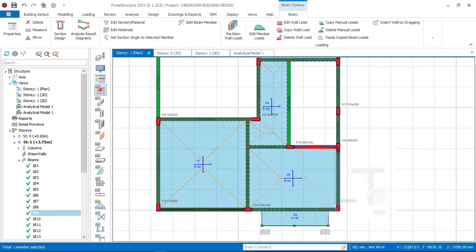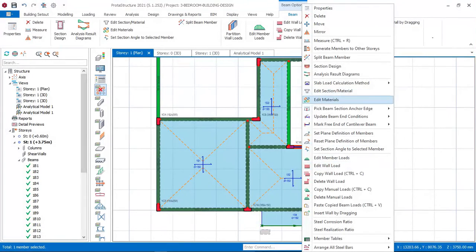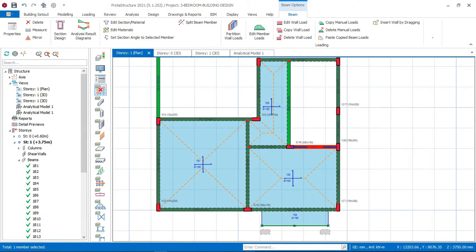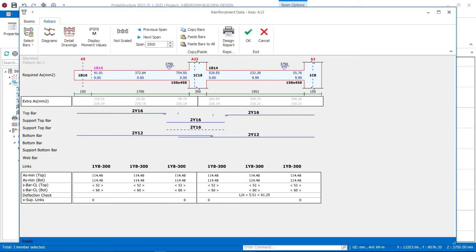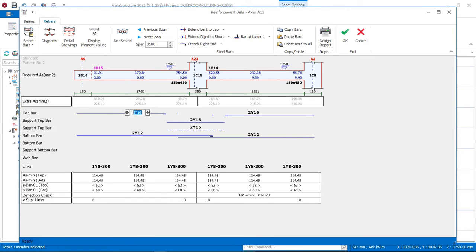So I'll check each of the beams, and then we'll also check the columns. Check this beam right now. I'll check all the horizontal ones. I don't like the way that this is. You can now see what is done here: they are giving you 16 up and bottom as under 12, which is not okay at all. How will your top bar become 16 and your bottom bar, which carries the load, become 12? It's not really nice, so I'll have to make it 16 also.